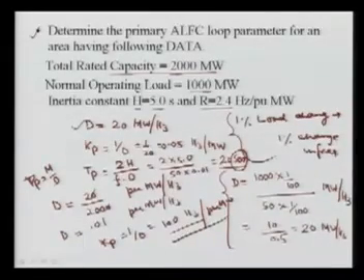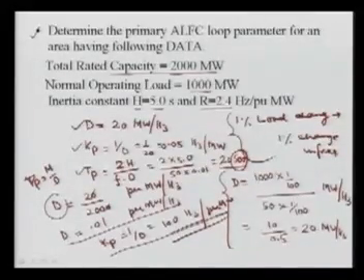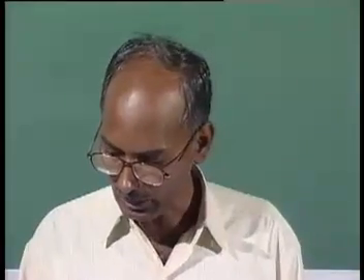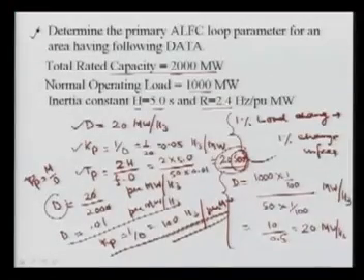Okay, let us see the previous example, means this example I discussed to calculate your dP, Kp, D and the Tp, and we obtained this D in the per unit here. This I got this value, and the Kp I got in the per unit this, and the Tp I calculated as 22 seconds. With this I want to calculate what will be the change in the steady state frequency if there is a sudden change of, let's suppose, 20% of the load. Or we can go for the 20 megawatt load and we can calculate what will be the change in the frequency.